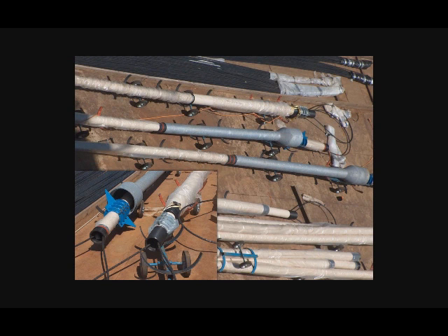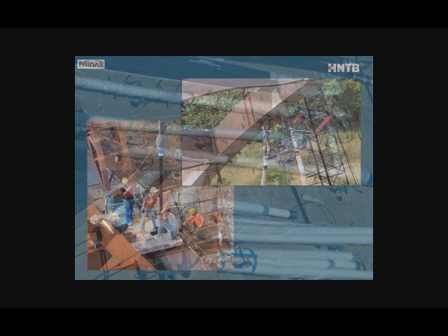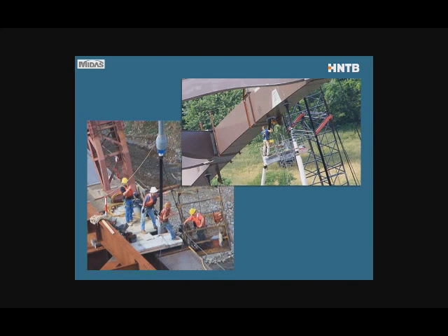Strand installation and cable installation, as I mentioned earlier, is done with very light equipment, one strand at a time. So here we are on the barge. The lower insert shows that one strand is installed. That blue device is just a collar to hold up the anti-vandalism pipe. You can see in the larger picture, you can see the cable with the anti-vandalism tube, and then transitioning to the HDPE pipe. So the whole thing gets lifted in, one strand plus the HDPE pipe, and then the next step is just one strand at a time is attached to a little winch system.